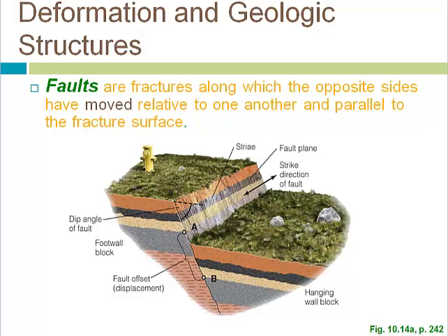Again, this is a normal fault because the hanging wall has moved down with respect to the foot wall, or the wall that you hang your lantern on has moved down with respect to the wall that you would be walking on if you were mining this fracture, which means if you're standing here, and you were to look up, the wall that you hang your lantern on has moved down with respect to the wall that you would be walking on.